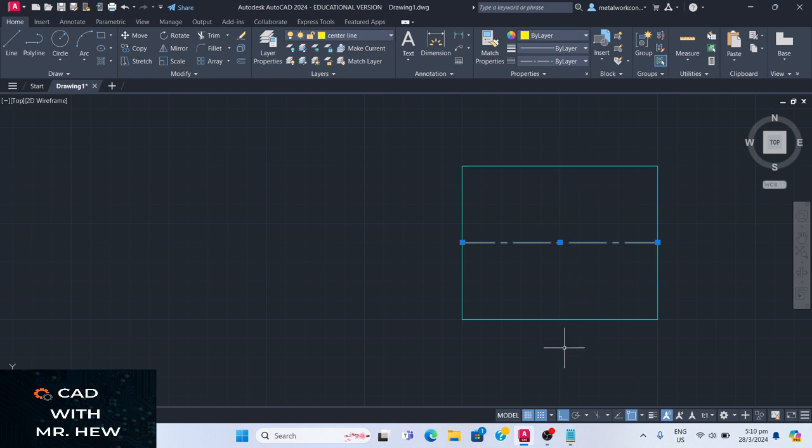We're going to draw another center line this way. So we come again, line, center, center, enter. Right? So that's our center. So this is how we draw basically in AutoCAD. Now what I'm going to do now, I'm going to draw 4 holes, well, 2 holes down here, the lower part of this rectangle. All right, so what we can do, we can offset this line which we just got, to represent the center line. So let me show you.